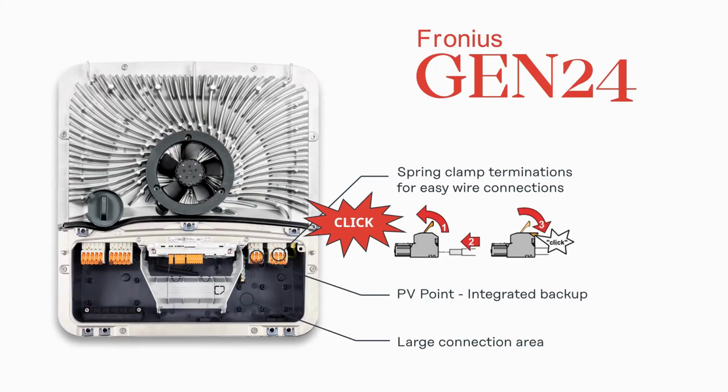So in the past, you see these inverters, you have to crank down on a lug. Here, you just open up a little orange tab. They actually come out of this inverter, so you just take this wiring compartment out, you insert your wire, clip it down, and then snap it in. It's extremely easy. It saves so much time when we look back at these inverter models, which required that large lug, and then making sure that we keep those values torqued at a certain time every year. It's just a mess. Here, we don't have to worry about this with these spring clamp terminations.